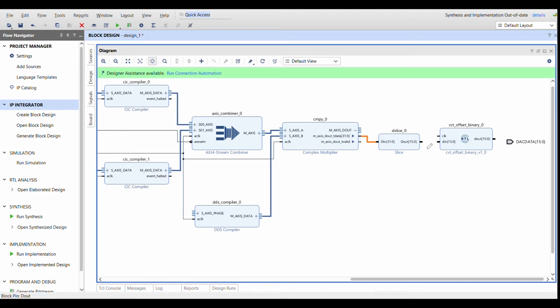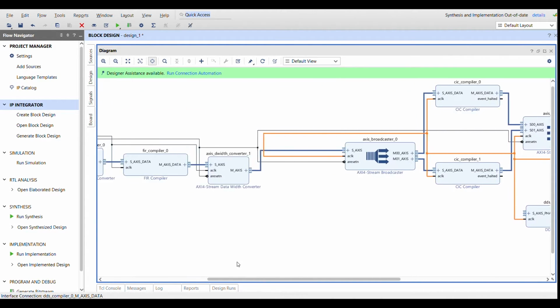Connect that up, and the last thing is a little bit of Verilog. This is a module which is going to convert it from signed magnitude to offset binary, assuming that's what your D to A converter requires. It depends on what your D to A converter is. That's connected to a schematic port, and that's then ready to go to output pins or to the simulator. By connecting it to a port, it's visible to something off the page. That's all the signal processing done.